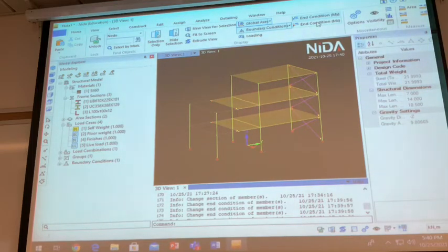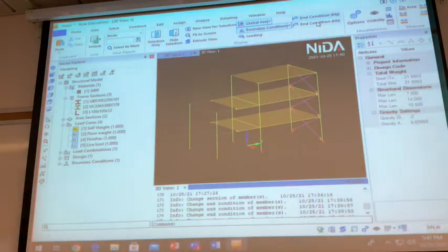Okay. So this boundary condition is the external redundancy, and this is related to internal redundancy. If you want to impose more external restraint, you make it become an indeterminate structure. But when you release it, you turn the internal redundancy into released restraint.